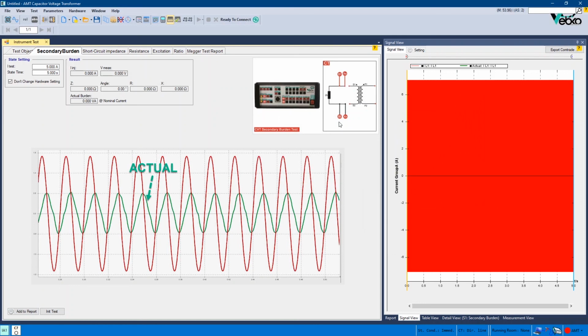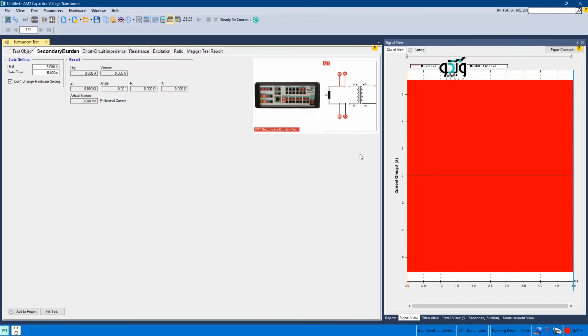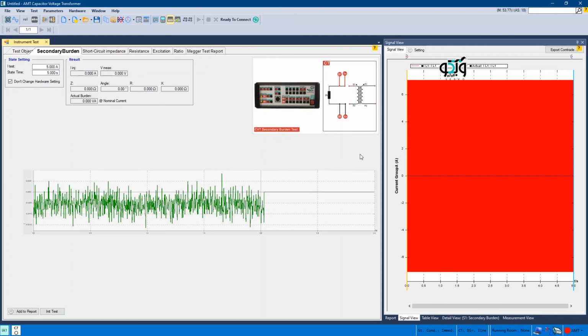If the current is injected by the device, but its difference with the specified current is high, this means that the path resistance is high, and if the actual current is zero, it means that the current injection path is open. Where the path resistance is high, the test current must be decreased, and in case of a zero actual current, the connection of connectors needs to be examined.